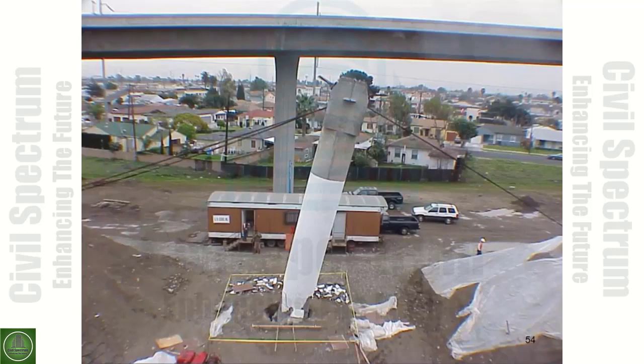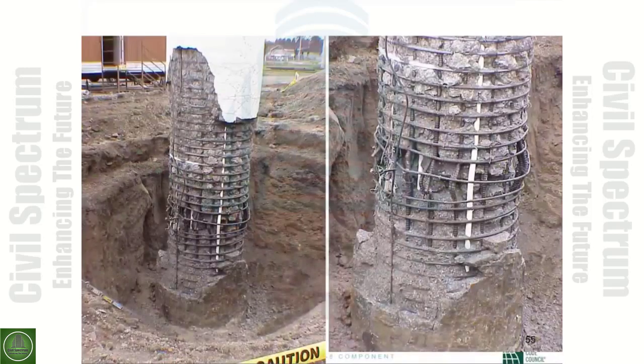For that one, normally it's 3D inside the ground. 3D is the diameter of the column. It will range between 2.5 to 3D, and that will be the location where you have the plastic hinge.